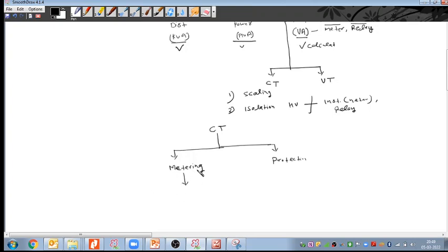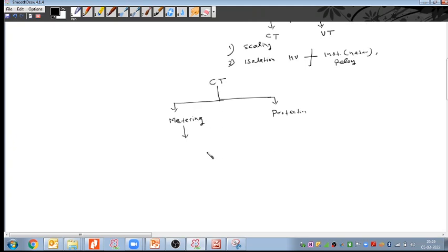Yesterday we discussed this metering CT, and also that in a substation or switchyard we use the multi-ratio and multi-core CT. Why is multi-ratio required? Because when we make any switchyard, the expected life is the next 30 or 35 years. Initially the current flowing is less, the loading on the substation is less, so we can use the lower tapping ratio.